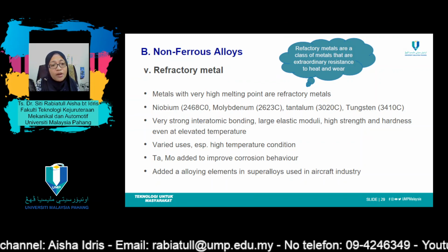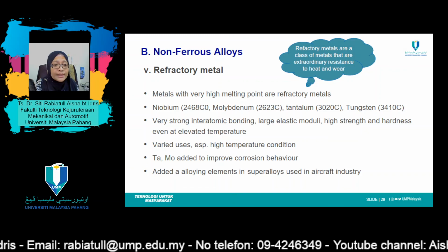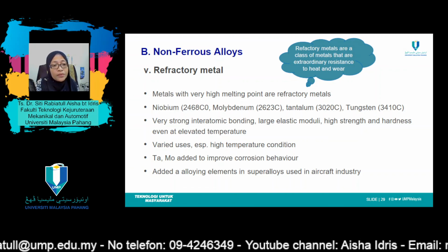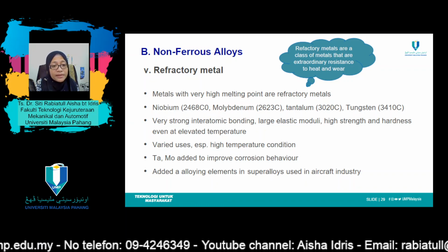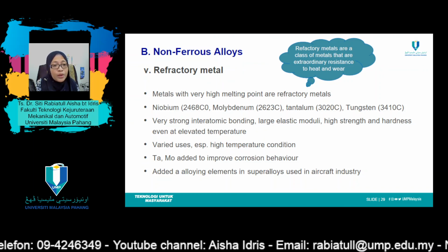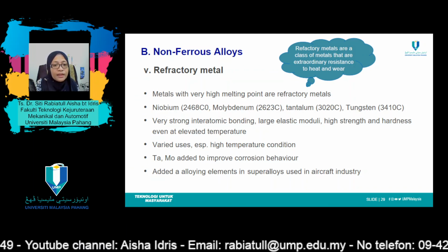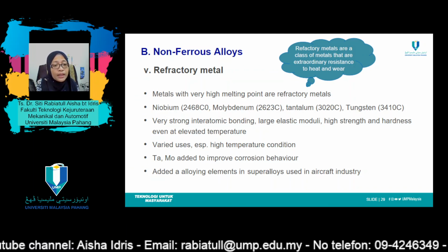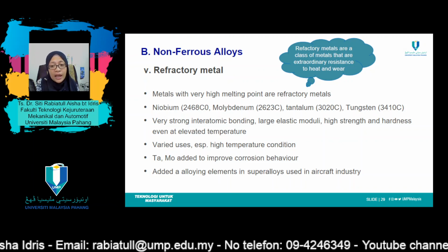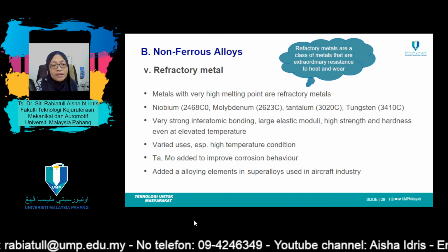The applications of these metals are varied. For example, tantalum and molybdenum are alloyed with stainless steel to improve its corrosion resistance. Molybdenum alloys are utilized for extrusion dies and structural parts in space vehicles. X-ray tubes and welding electrodes employ tungsten alloys. Tantalum is immune to chemical attack by virtually all environments at temperatures below 150 degrees C and is frequently used in applications requiring corrosion resistant materials.